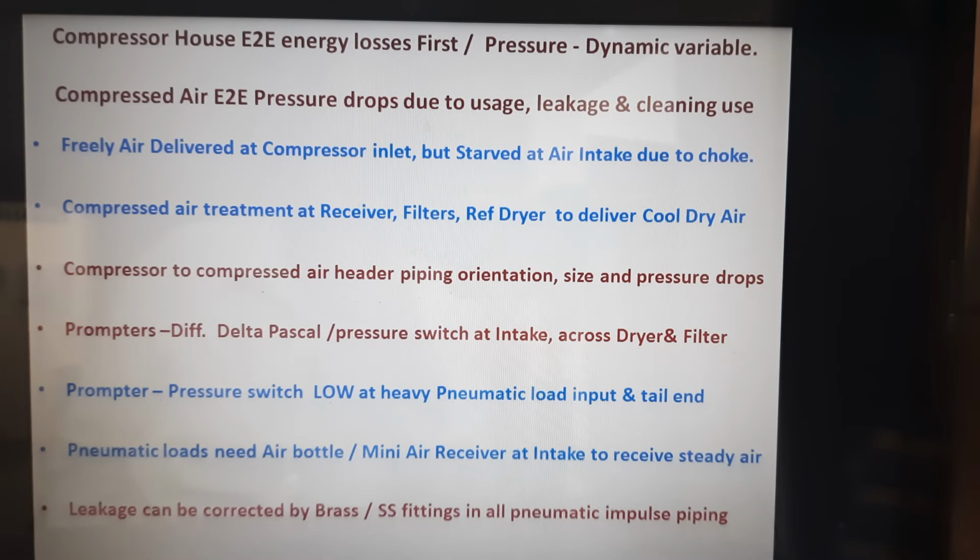Next comes the cleaning air. The cleaning air application definitely needs a buffer receiver and scheduled cleaning to be taken up by the plant. When you are planning your maintenance, this cleaning also needs to be scheduled. Also, the buffer air receiver sees to it that the pressure drop does not happen at the compressor, and the compressor is not put under extra strain because of many hoses being opened for cleaning at the same time.